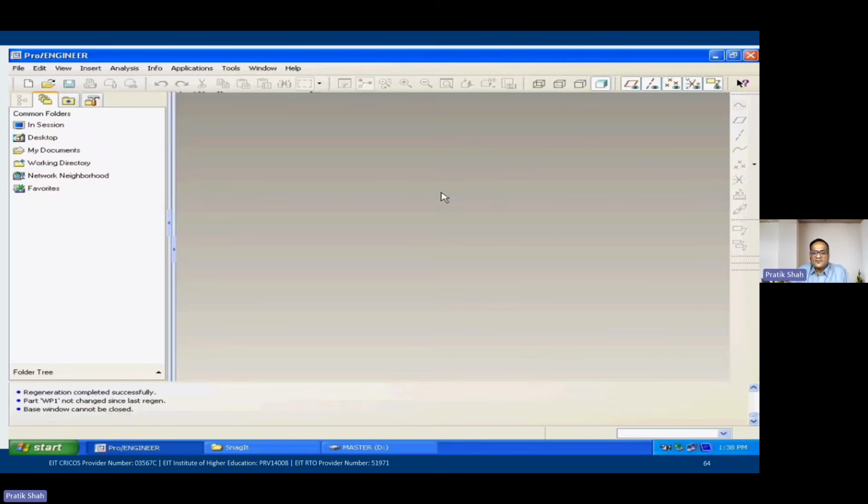I'm naming this cut as rough cut because normally we do two major cuts, the rough cut and the finishing cut. So the rough cut would be having a lesser, I mean more rake angle compared to a finishing tool. That is what I did. I am now setting the depth of cut.